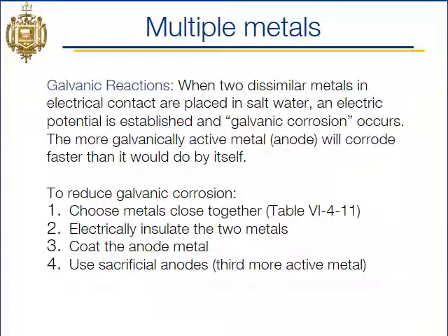It's actually a pretty prevalent problem. The Navy's experienced this problem with the LCS. You've got an aluminum hulled vessel, and it has steel cross bracing, and where the steel connects to the aluminum on the ship, if that gets a little bit wet, it causes this galvanic corrosion. And they've actually had issues where holes have opened up in the side of the LCSs because of this galvanic corrosion. So one way that the Navy has at least dealt with this is they've used zinc sacrificial anodes.